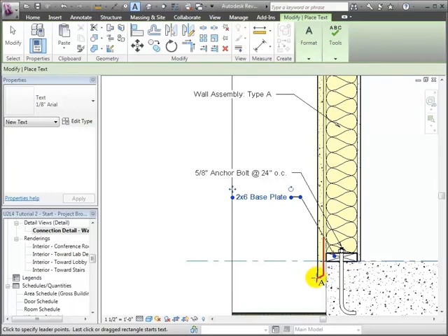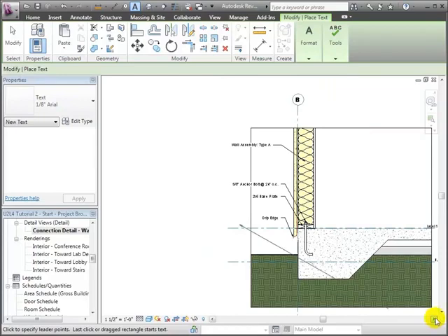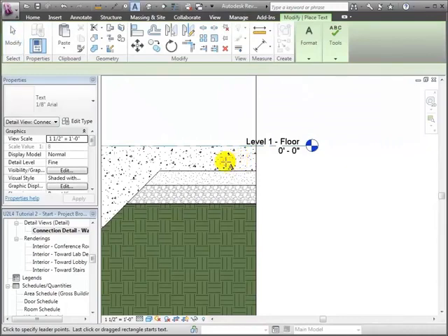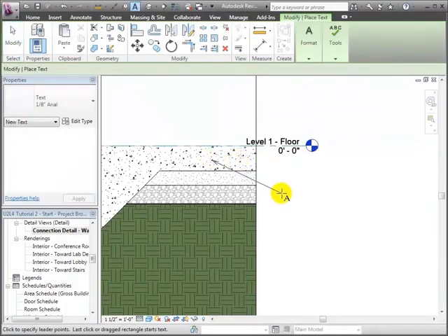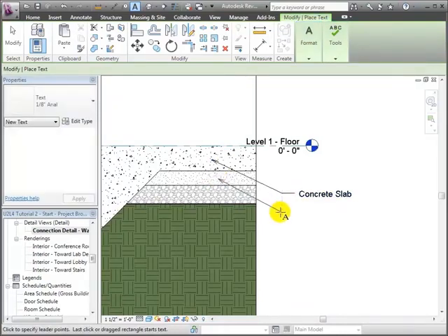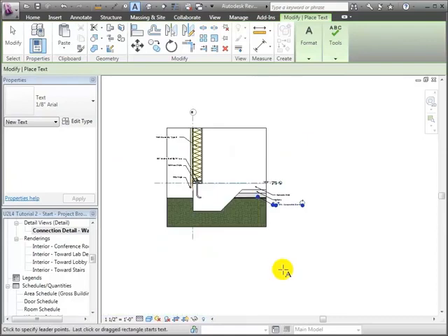Finally down here, let's go ahead and call out the special little drip edge piece that we put together. Let me zoom out. This might be a good place to right to there. Okay, and now we'll say that great. This is going to be, what is it? That's our concrete slab. In this case, I'm going to shift it over to be left justified though instead. This is going to be our sand. And this final piece down here is our 3 inches minimum compacted gravel.